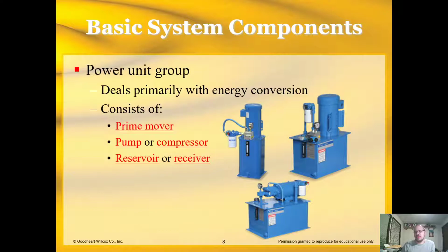Okay, the power unit group. This is the first group we discussed, and it deals primarily with energy conversion. Again, the big thing for hydraulics is energy conversion. It consists of the prime mover, the pump or compressor, and the reservoir or receiver, depending on whether you're pneumatic or hydraulic. This is what actually moves your fluid.